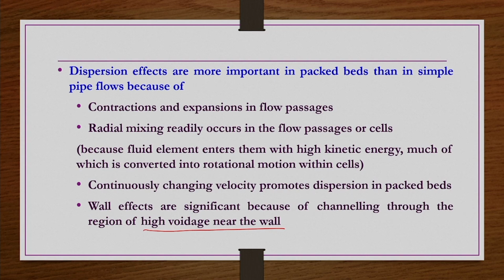Because of these many reasons, we have seen that dispersion is very much essential in the case of a packed bed, if a column is packed with particles rather than only an empty column. If there is an empty column, dispersion may be very small or negligible in many applications, but if the column is packed with particles, then dispersion is going to be very large, and one cannot avoid considering it in engineering calculation, either for the design of the equipment or for tuning of the operational parameters. So, why does it happen in the case of packed beds? Because of these many listed reasons.